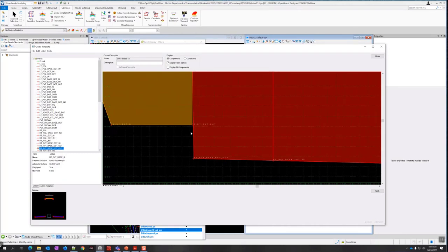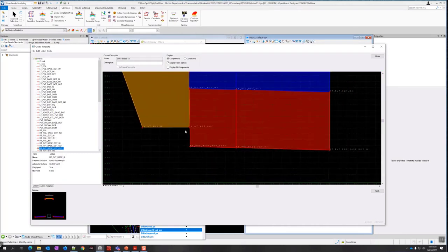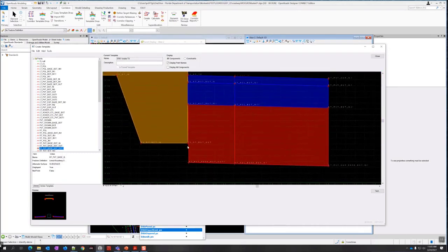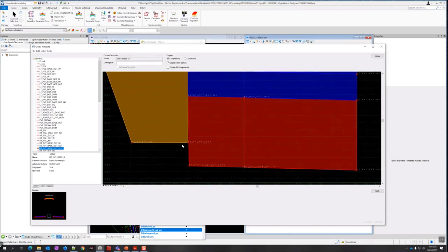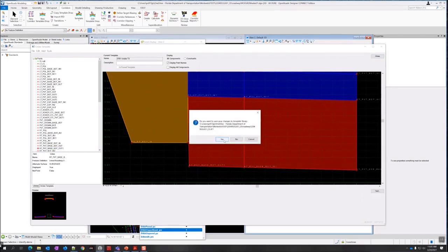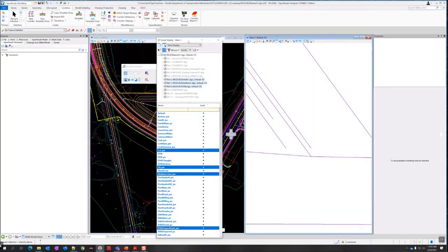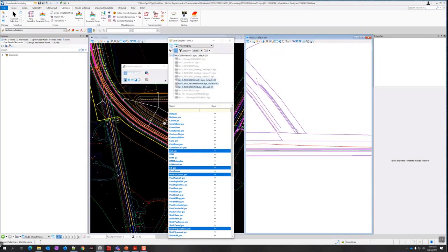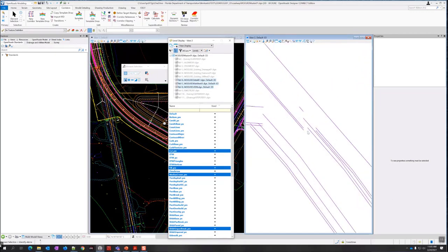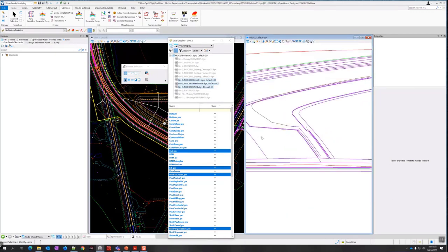Now by the time you see this, I might update the data set to correct this, but this way you have a sense of what you need to do if you have an issue. So you'd have to go in and synchronize that template. I'm gonna save the changes to the ITL here, and you have to go synchronize the template. I'm gonna leave it right now and just build it like it is. Remember, we're going to edit the break line, so you can also make edits there.